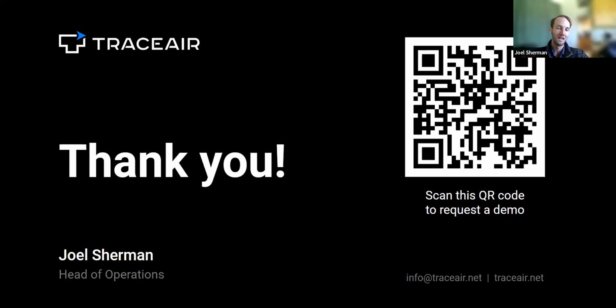But really it's not an accurate assumption, in the sense that there might be some deeper contouring, or we don't know what kind of depth of contouring is happening in that water area. So yeah, best to have our LiDAR data acquisition occurring when there's the least amount of water on site to get the most accurate profile. But if the ponding size is pretty small, then the amount of deviation from reality really isn't that significant from our perspective.